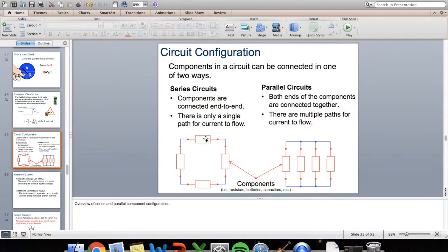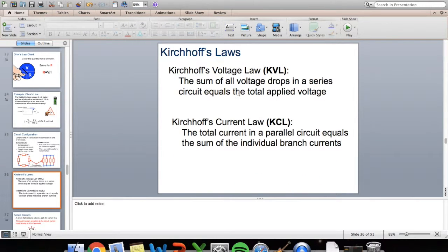And right here in a series circuit, let's say this one's the battery, right? And it's pushing around. So all that water, 1 gallon of water, or rather 1 amp of electricity, is flowing around that circuit, right? And it's not going to get split up into thirds, but our voltage is going to get split up, right? So maybe 1/3 of the voltage consumption happens here, 1/3 of the voltage consumption happens here, and 1/3 of the voltage consumption happens there. So that's what that's saying.